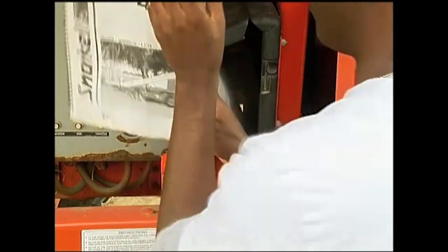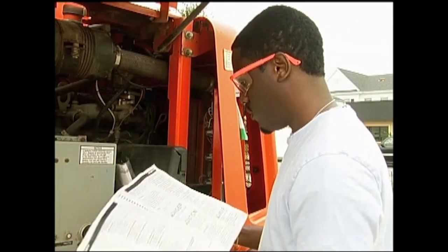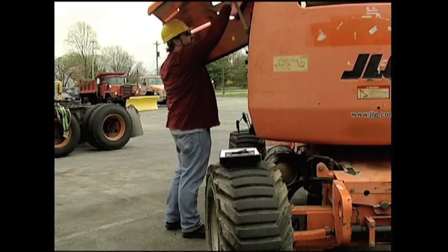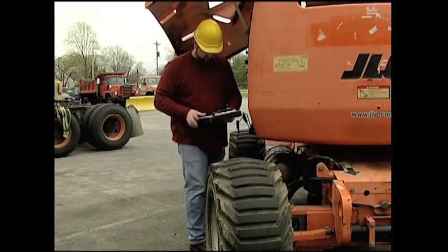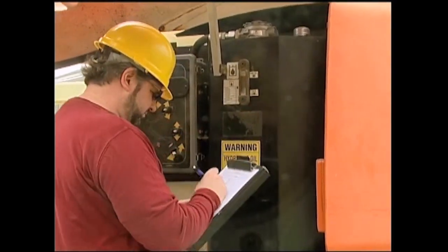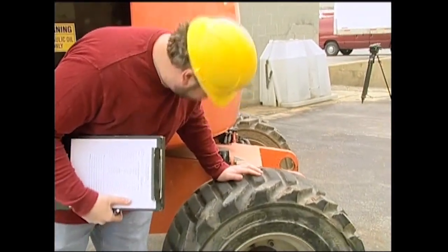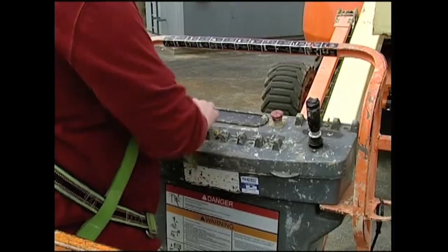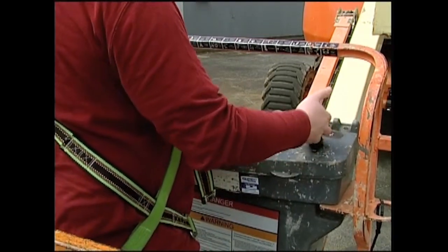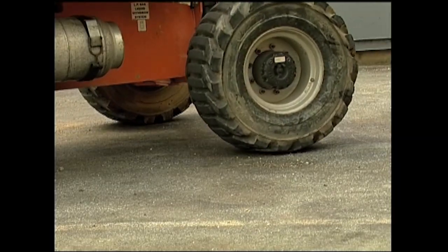You'll find a list of things to be inspected in the operator's manual. It's been compiled by the equipment manufacturer and should be followed rigorously. However, there are a number of things that you should look at on any lift. Check that fluids are at their proper levels, wheels and tires are not damaged and are properly inflated, and the battery and charger are in good working order. Confirm that the controls operate correctly and that the horn, gauges, lights, and alarms work properly. Test the steering and brakes as well.